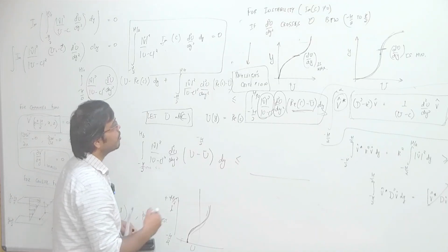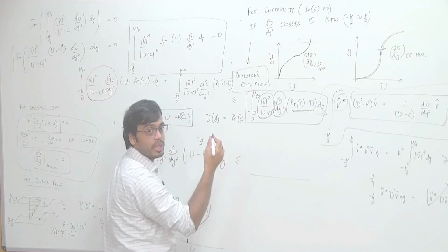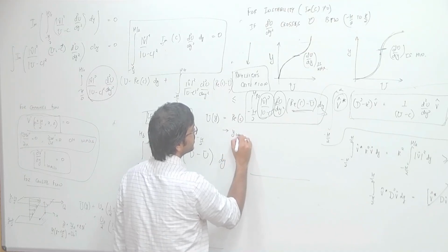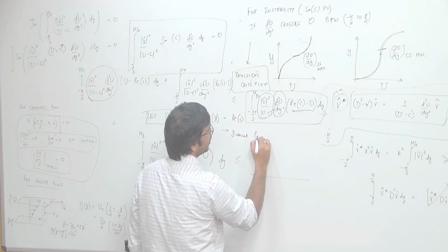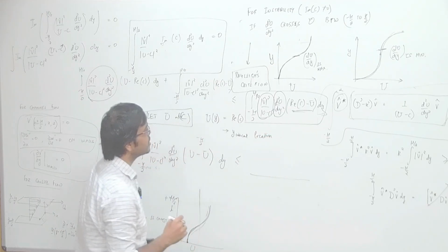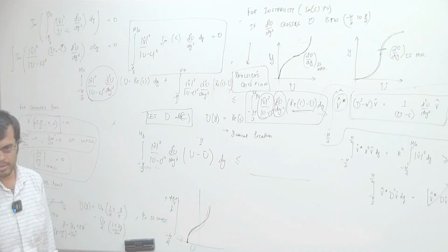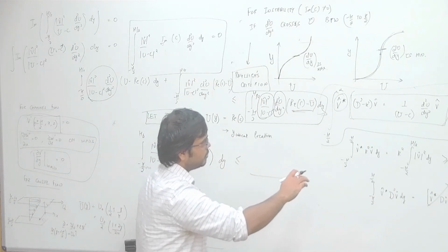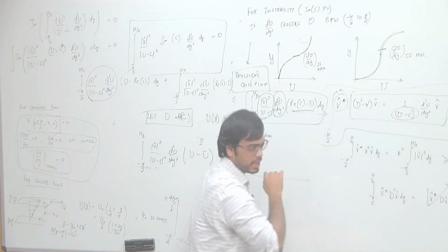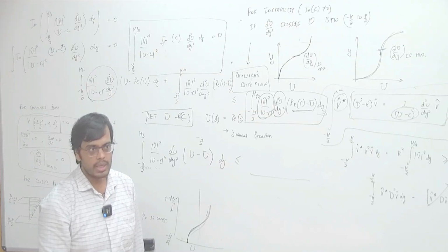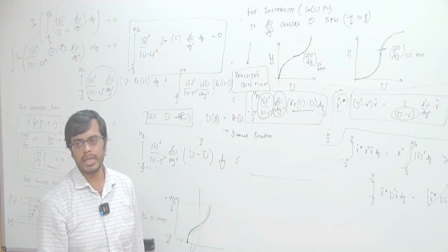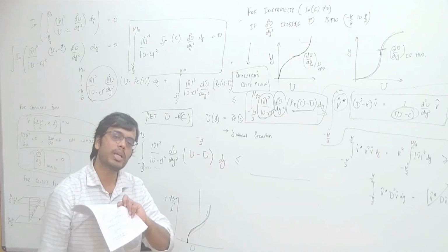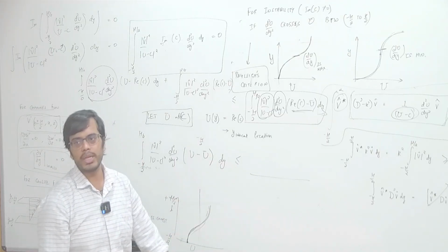Okay, and this particular y location where you have u equals u bar is called the critical location. Now, this has very important implications. What happens near this critical location? As you will see in some advanced instability textbooks, there are problems that start appearing here. Things start to become singular near this critical layer, and you have to entertain the possibility of viscosity in your perturbations. No matter how smooth your perturbations are, you have to entertain the possibility of viscosity.